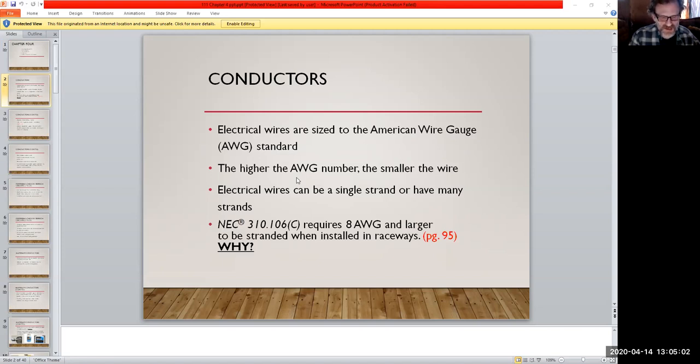If you're trying to bring your wire in and have it go through a 90-degree bend, good luck with that. That's the reason why. It's just like a copper rod at that point, and it'd be great for a grounding purpose or something. But trying to run that through raceways with any kind of bends, 90s or even 45s, you're not going to do it.